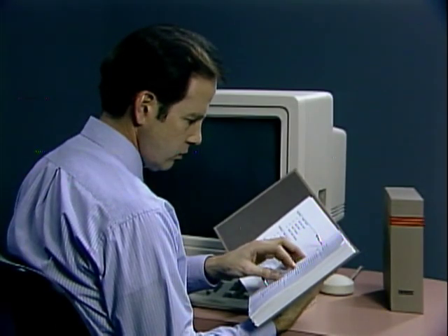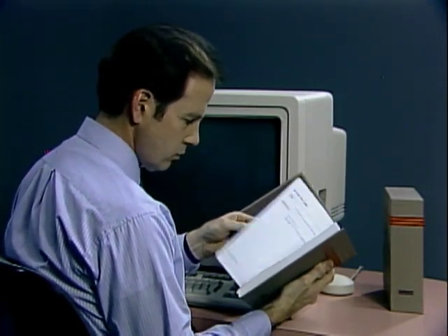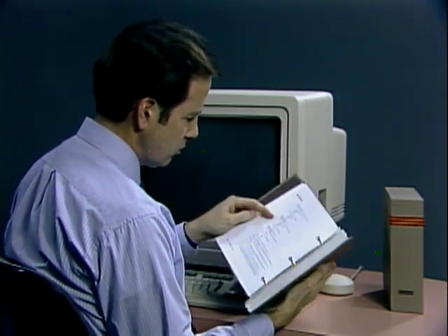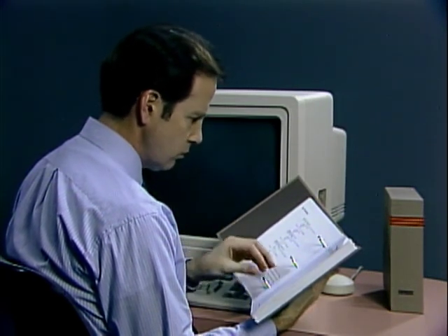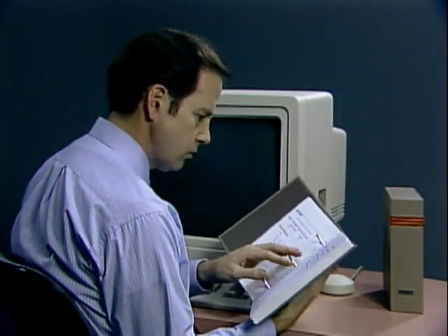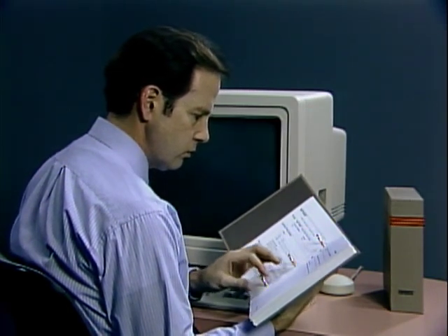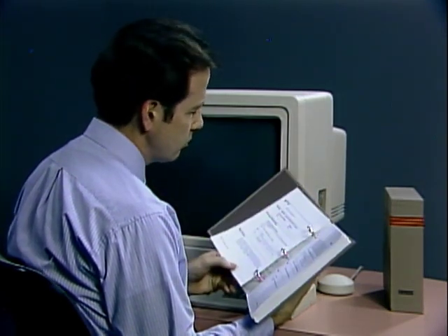In this lesson, we will discuss the procedures used to troubleshoot problems in the VAXstation 3520-3540 workstation. The Power-Up Self-Test, or PST, will be your primary tool in determining failing FRUs and verifying fixes. The first section of the PST, tests F through C, checks initial system integrity and establishes the primary CPU.